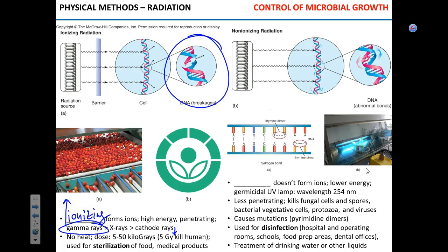You know, try to boil the hamburger. Okay, so that's why gamma rays are used for food irradiation. Things like fruits are often, obviously not sterilized, but the bacterial load on their surface can be decreased, so the storage time increases. Does that make sense? And it's convenient, you don't have to load batches. You can just irradiate on the conveyor belt.